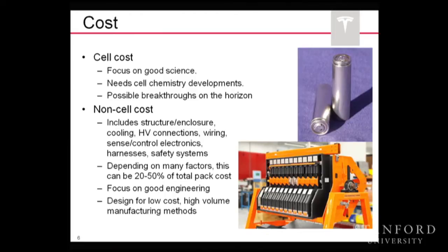They are, for your money, the best deal in town, except for lead acid. But there's not a single car out there, except if you go to an obscure build-it-yourself site, that uses lead acid battery packs for vehicles. The only vehicles around that use those are forklifts, and they use them because they needed ballast weight anyway. So putting 1,000 pounds of battery on the back of this thing just to hold it down is a good thing. And for the dollar, they also deliver a lot of power. But these lithium ion cells are certainly the best thing in terms of vehicle use. The other big cost to a battery pack is all the ancillary stuff.